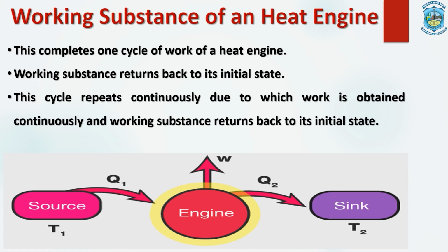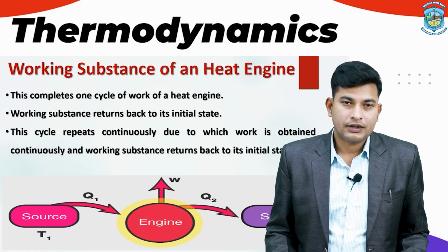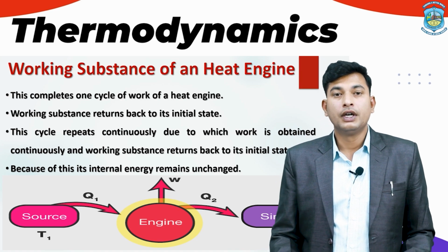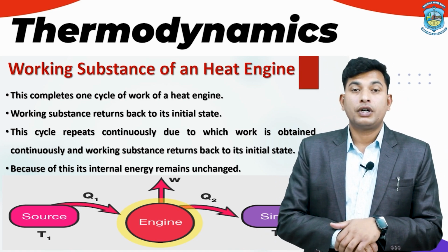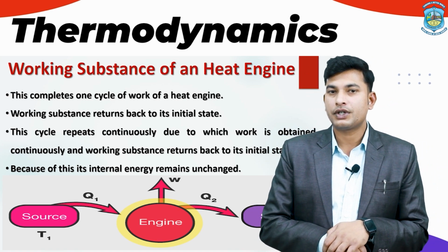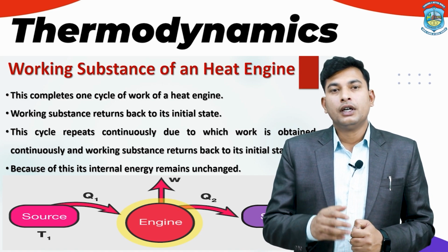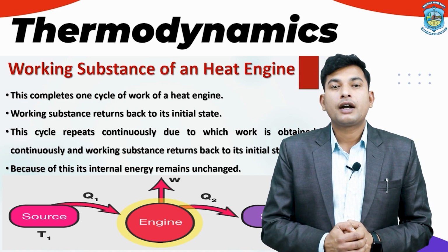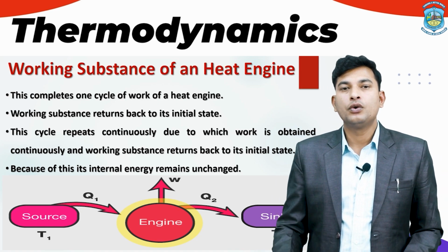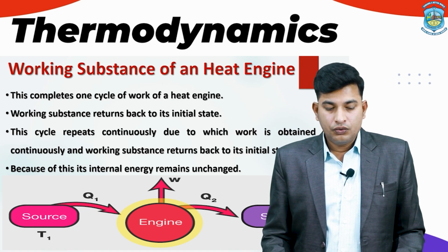because it is a continuous cyclic process, and we are seeing that the substance is returning back to its initial state and temperature is remaining constant. So, as we have discussed in the previous lecture, according to the first law of thermodynamics, if temperature remains constant, as in this particular section I have zoomed about the isothermal process, in which the temperature is not getting changed, it means there is not any change in internal energy also. The internal energy will remain constant, and the change in internal energy will be equal to 0.